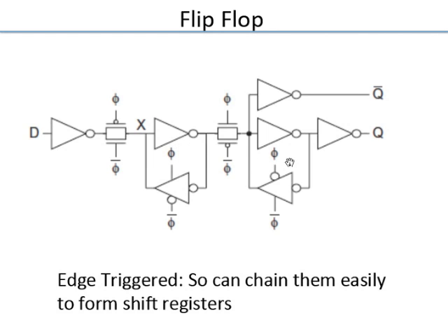By putting two of these back to back and then operating them with inverted clocks, you obtain an edge triggered operation, because you have the master latch and you have the slave latch. You notice here in the slave latch we have removed this inverter. There is no need, because it's protected, it's kind of inside, this can itself drive. So we don't need the input inverter here, and we don't need the output inverter from this latch. So both of those have been removed.